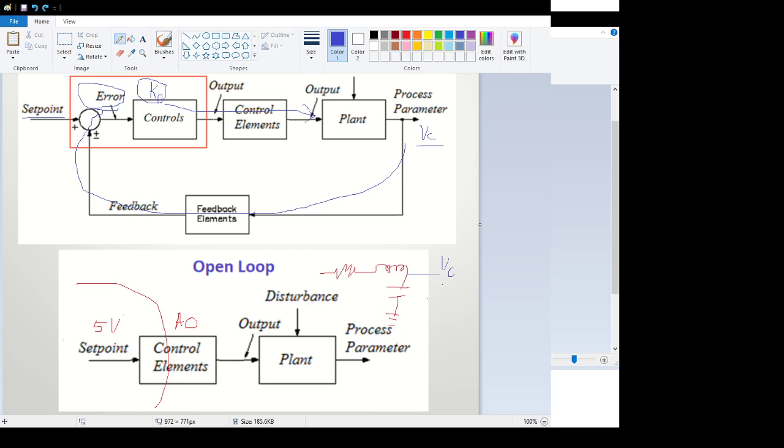Now, I've already built the program and have it connected up and running here. And I'm just going to walk through some of the ladder logic. So notice that up here at rung 0, I have no contacts on the left-hand side. So this means this is going to happen every single scan. What we're going to do is we're going to read in the voltage across the capacitor. Every scan of the PLC, we're going to read in the voltage, which is coming into channel 0. So you see there it says local 4.